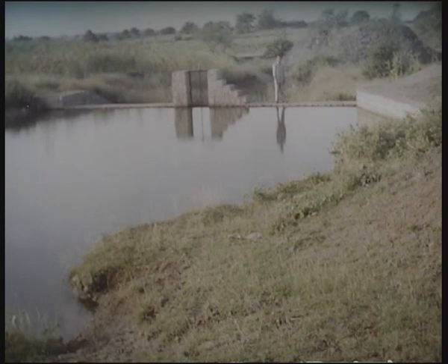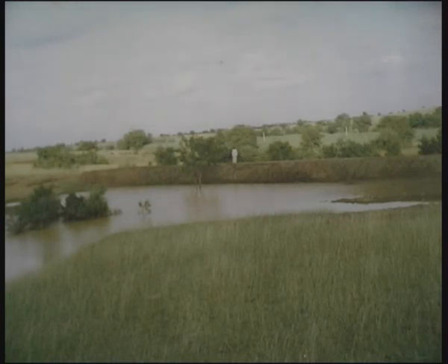Now, there would be a necessity for constructing check dams in the tributaries of the main stream. In such cases, such check dams can have an earthen dam in the stream course and surplus arrangement at the ends, like in a percolation tank. In a percolation tank, the entire structure is an earthen dam and the spilling arrangement would be at the ends, and there would be a surplus course formed from the spillway to the deep stream course.